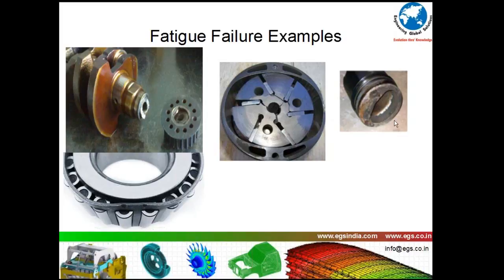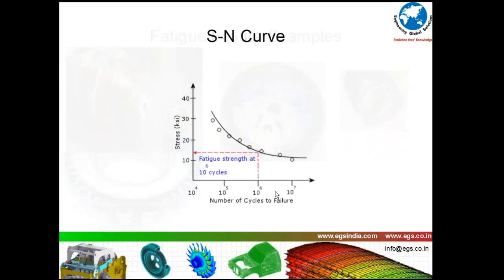Now, it is important that when we look at these kinds of costly warranty failures, we need to understand that these eat into the profitability of our organization more so than ever. When you look at any design, fatigue means we are looking at the stress versus the number of life cycle curves, with factors with regard to the fatigue strength. I'm going into the technicalities a little bit over here, primarily because this is important for us to understand. It is not the factor of safety, it is the life calculations.